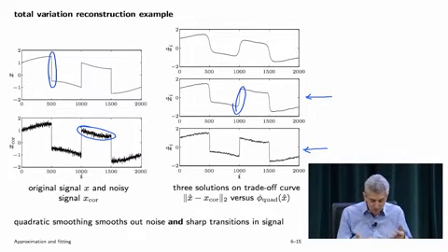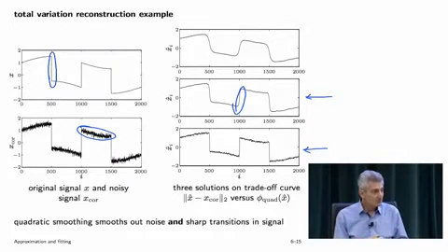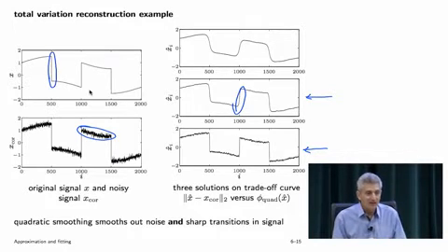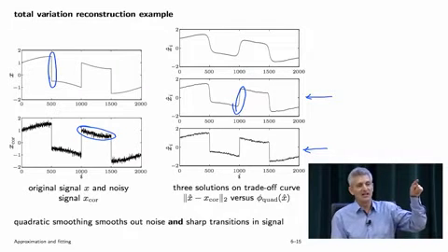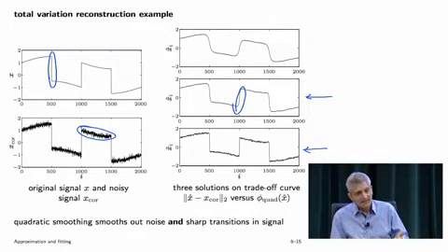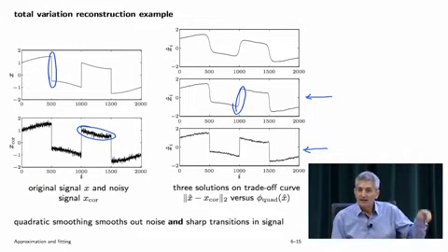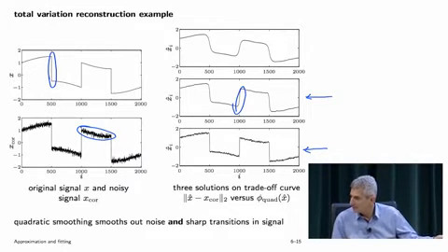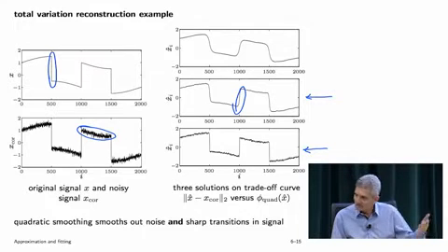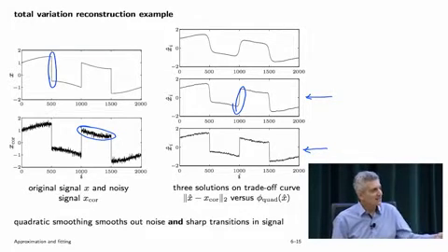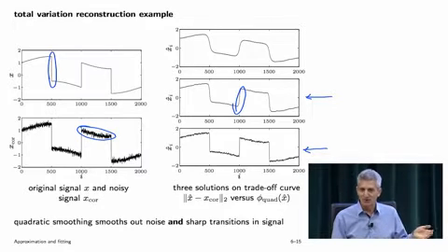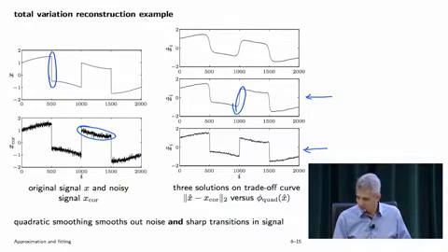By the way, if this were audio, this would make something sound very muffled. If this was the attack caused by a drum, right? Someone hits a snare drum, you will get something that looks like that. And if you smooth it like this, instead of the attack rising in 10 samples, at 48 kilohertz or something like that, it goes over 1,000. It sounds like a thud, and it doesn't sound like a drum anymore. Okay, so all right.